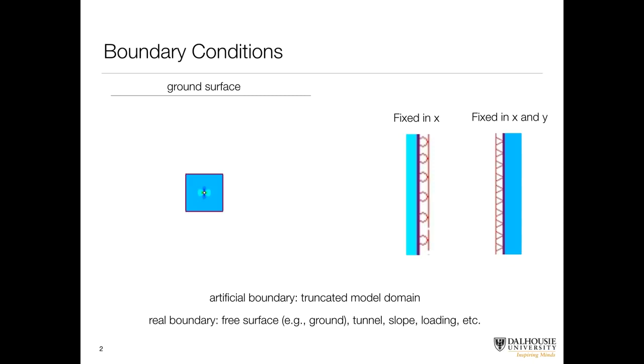Essentially, the model domain has to be zoned with a mesh full of a number of elements. And the more elements that you get in it, the more computational effort it takes and time it takes to carry out that calculation. And it tends to be an exponential relationship, the relationship between how many zones you have and how long it takes to run.